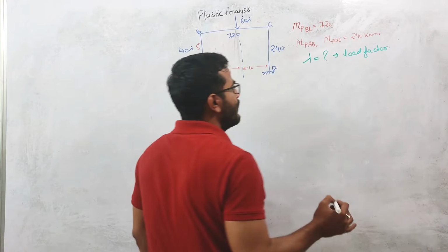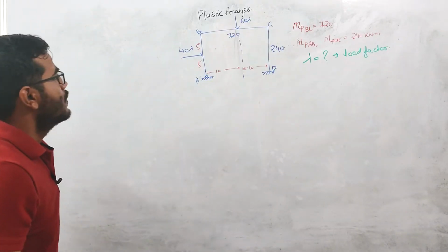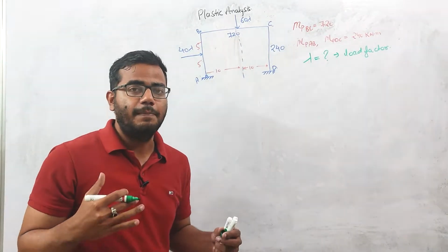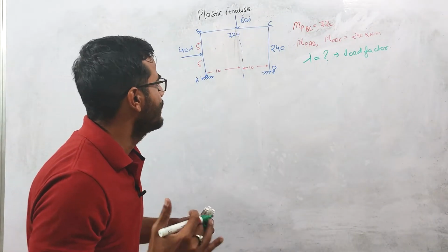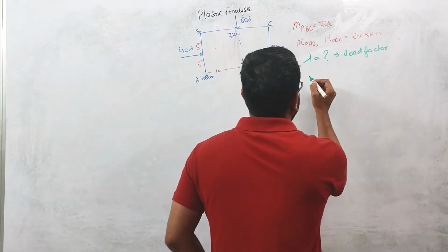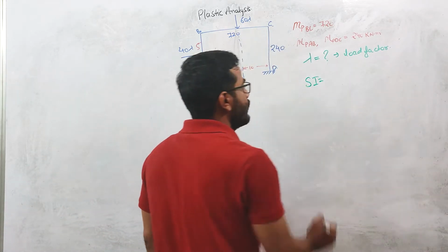Okay, what is load factor? We have already discussed, right? So basically, to find the value of load factor, the first basic step in the plastic analysis is to calculate the static indeterminacy of this frame. Okay, what is the static indeterminacy of this frame?